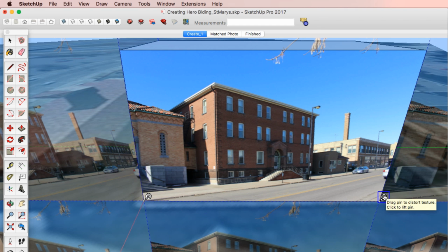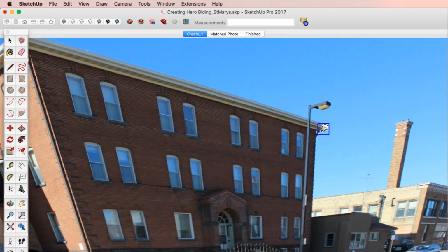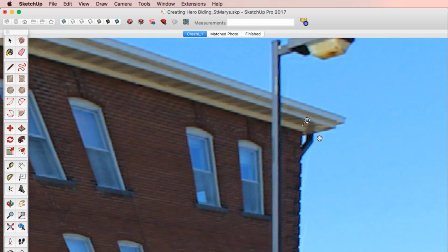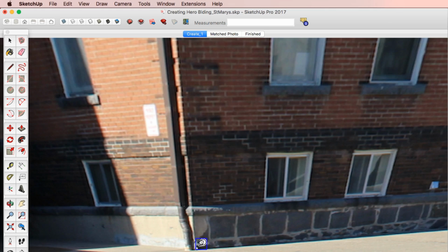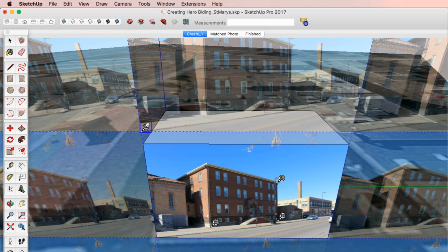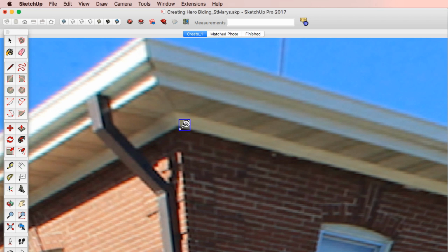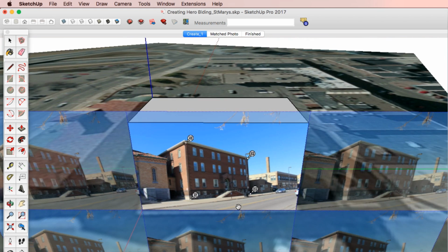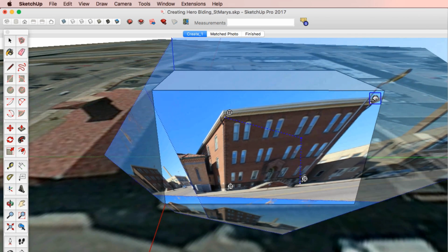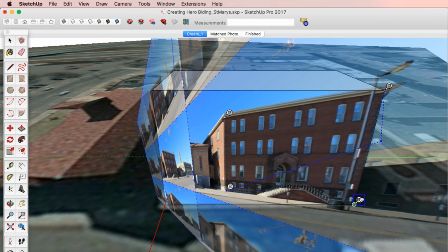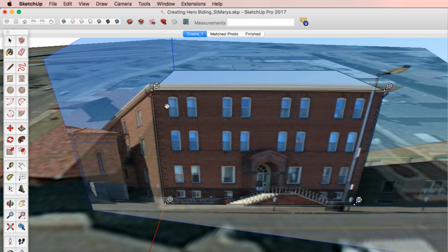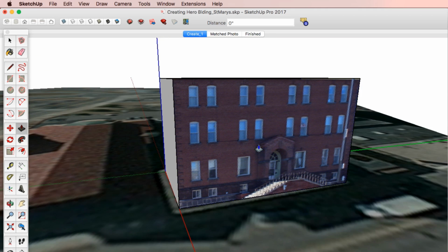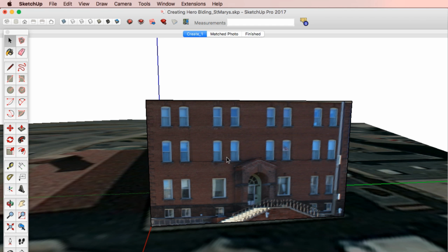So I'm going to use another tool. I call it a texture tweaker. If you imagine the photograph being glued to a rubber sheet, and then you take these pegs and you just jam them right into the rubber sheet, and after they've been positioned according to what I see in the photograph, I can just drag those pegs and have them stretched to fit the front of the facade, just like one would do with a rubber sheet. Okay. This helps me provide a lot of detail to the model without me having to do really anything. It's all in that photograph.